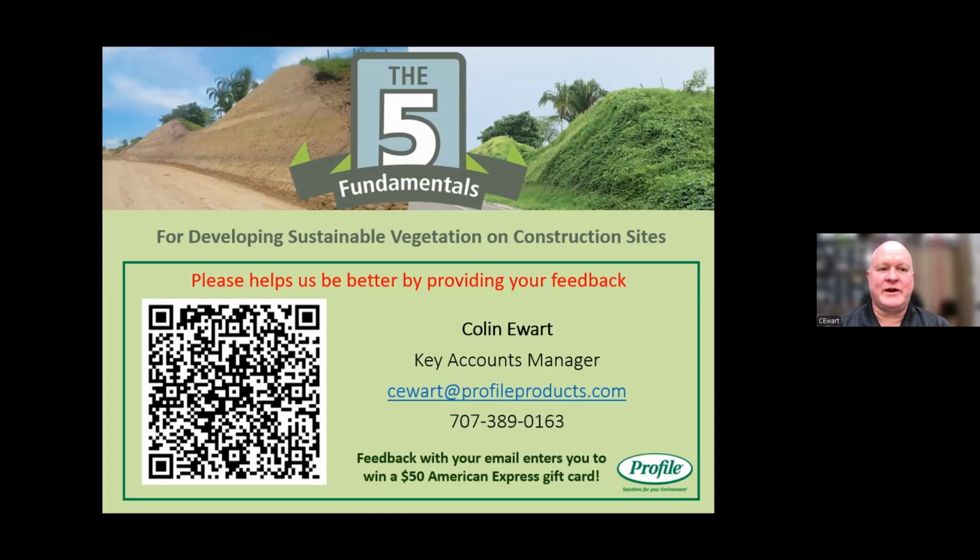Yes. That's an interesting one. When I was a contractor, I worked on a project in Napa, and we had beautiful clean water running through the property, and there was a vineyard basically uphill from this project, and we found water running on initially, so we blocked it, and we sandbagged it and diverted the water so it stayed on their property and didn't come onto ours. The following day we came out after a rain event and there was dirty water, and basically the workers in the vineyard had removed our blockade to allow the water to run back on. I would say there's a couple of things to do. Either convey the water through the property, through piping or ditching or some other conveyance. You can even create a ditch with visqueen. Otherwise, your best option is going to be something like straw wattle or compost sock, to put laterals in to slow that flow down and spread it out in sheet flow. It probably is the best solution for spreading out sheet flow.